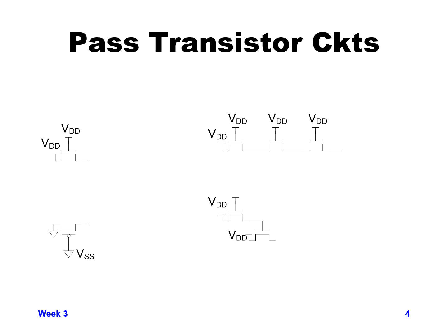So what value can we get out of this pass transistor connected with the gate, and you can call it the drain or the source, connected to VDD? The output in this case, we said from the previous foil, is the output source is going to equal VDD minus VT, which is the highest voltage that we can get out of that.